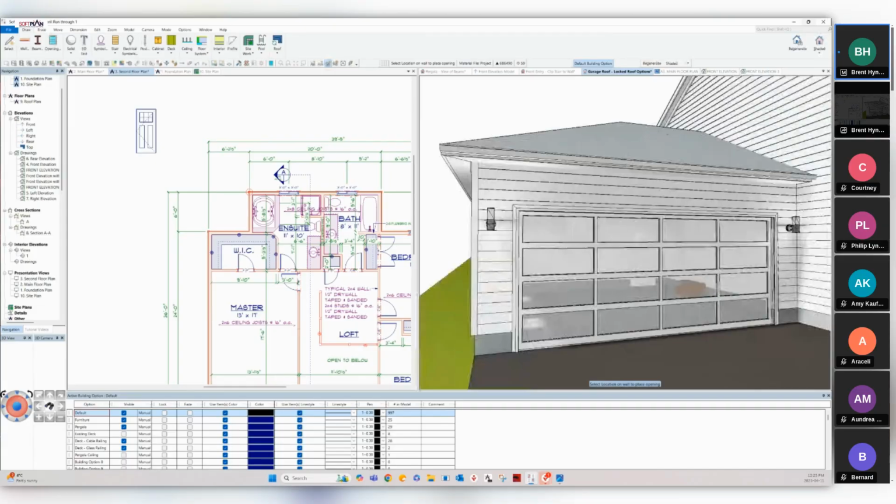This is a good example of one that we have actually defined using the new tool. And you can see this was just defined as a 4-light wide glass door, but it could be 16 feet wide or it could be 9 feet wide. And the glazed areas will stretch, and the rails and stiles in between will remain their current width. All right, so it's a good example. We will filter some of this through some of the other libraries. Currently, there are some modern doors added and that sort of thing using this tool, and the glazed garage doors have been done that way.